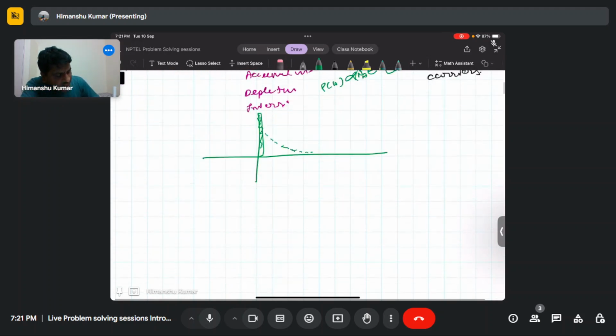And on the other side of the dielectric interface, there will be a negative charge buildup. As you can see, this is minus q and this is q. And if you know from 12th class physics, if two sheets of charge are separated by some dielectric material, let's say epsilon ox, then it forms a parallel plate capacitor.